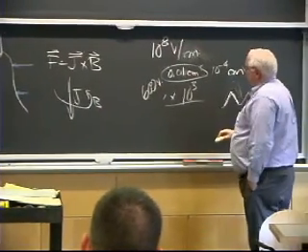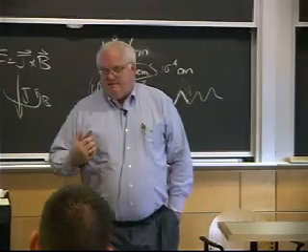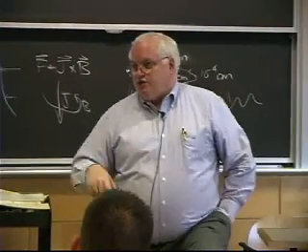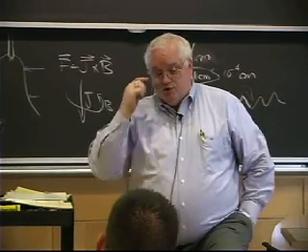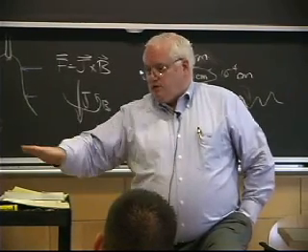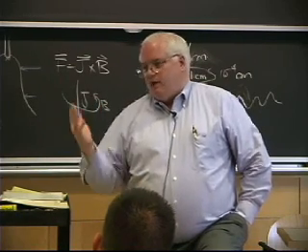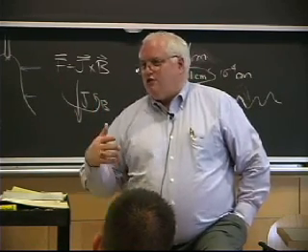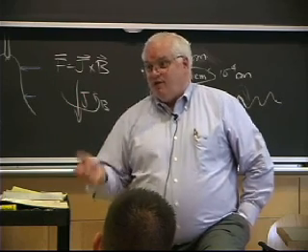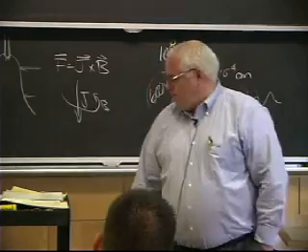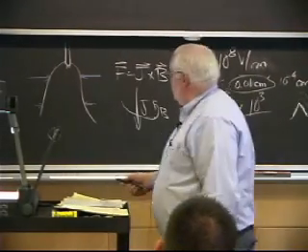It was something that was really sharp, and that could explain the extra difference in terms of the voltage. And in fact, they did have field emission, and all we had to do to prove it is we just did an electroless nickel plate on these things after they machined them, and then put the stuff on. The electroless nickel plate basically buried the oxide inclusions that they had machined over, and all of a sudden the spots went away. Of course, the problem was you couldn't afford to do that because that cost an extra $1 or so, and the margin on rebuilding laser cartridges was kind of small. So it didn't really solve their problem, but at least we knew what it was. It was field emission.